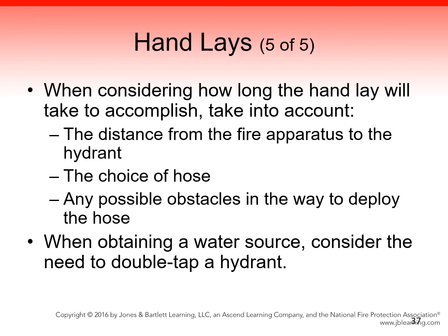If you anticipate that additional water may be needed, place an appliance such as a gated ball valve on the dry barrel hydrant prior to opening the hydrant. If additional water is needed, a supply line can be connected from the valve to the intake of the fire apparatus. Always follow your local SOP when obtaining a water supply. Only with practice will you build confidence and become more proficient in securing a water source. Follow the steps in Skill Drill 11-2.